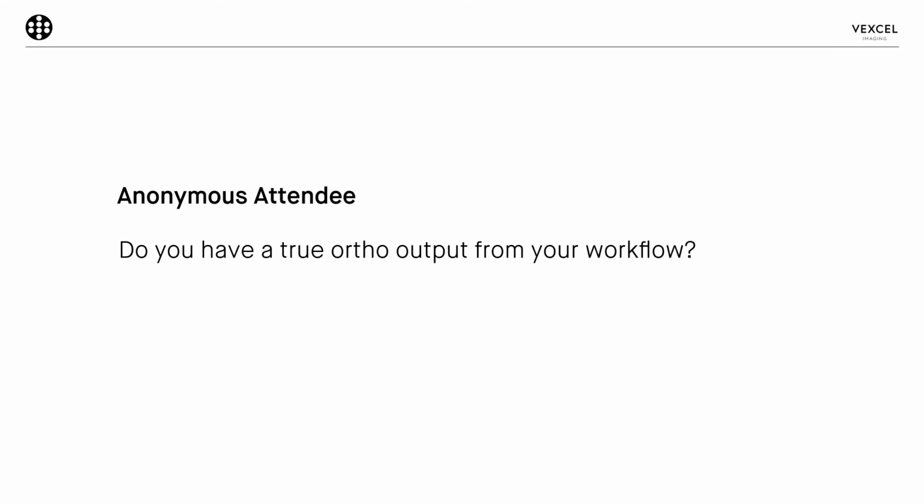Thank you, Bernhard. Another question: do you have true ortho output from your workflow? Yes, we do. In the ortho pipeline module, we can either do a projection based on the terrain model, the DTM, which gives the classical standard ortho imagery, but we can also do a projection based on the DSM, and this leads to what we call DSM ortho image, or another word, true ortho image. So the answer is yes. Bernhard, any details to be added? That's it. That's fine.